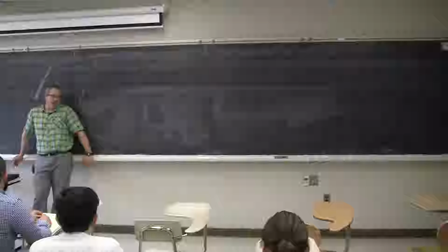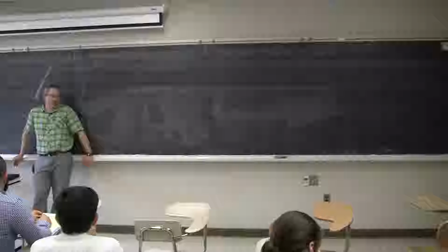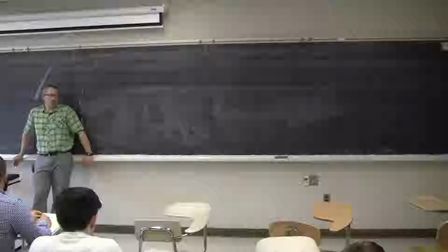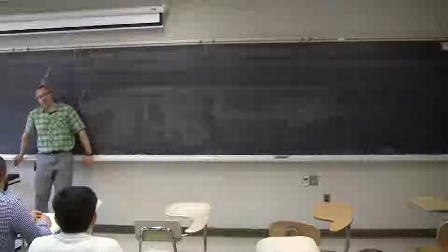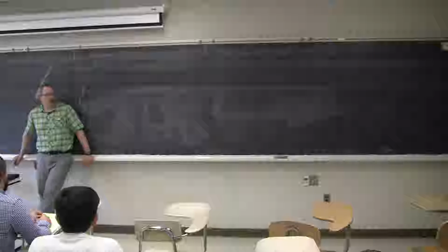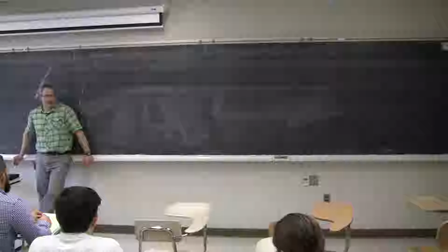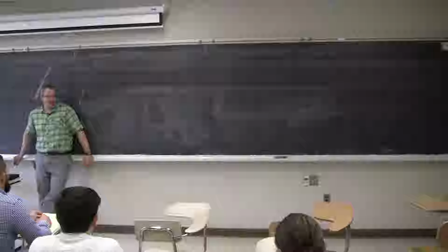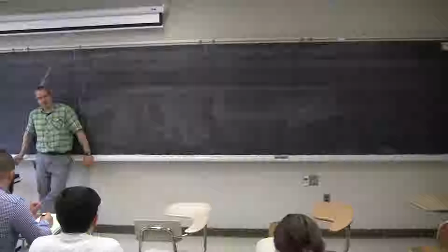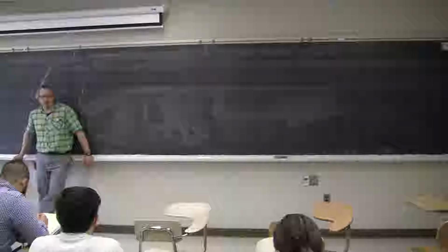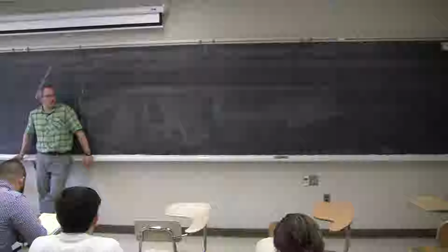Because of that negative is how we have to do the conjugate term. Okay? So your power triangles should always be in the opposite direction of your phasor diagrams. Your phasor diagrams are going to point down, right? So if voltage is my reference, my current points down, my S equals VI conjugate, my power triangle should point up.